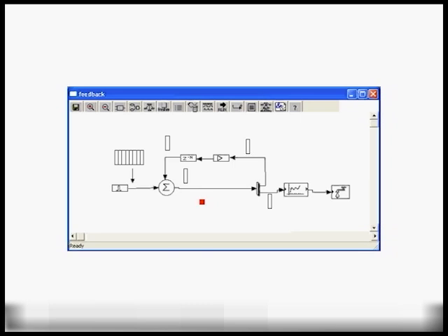So in order to support feedback in Capsim, and this goes back to Blossom, the delay block is a special block, in which case, even though the first time it's visited, even though it has no input sample, it would output a sample. And for a delay block to operate correctly, it would actually output a 0 sample. So this is special to the delay block, and we won't get into the code for that, but it's handled very efficiently in Capsim. So the delay block, once it's visited, even though it has no samples at the input, it would actually output a sample, a 0 sample in this case.